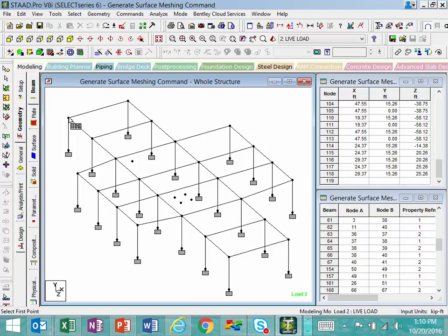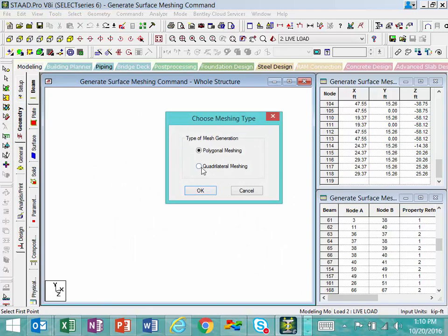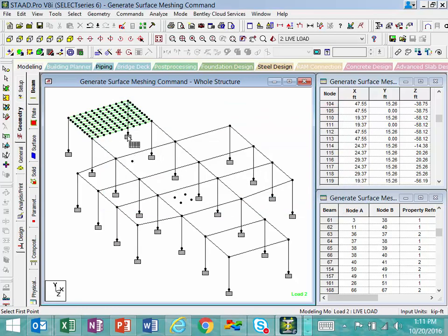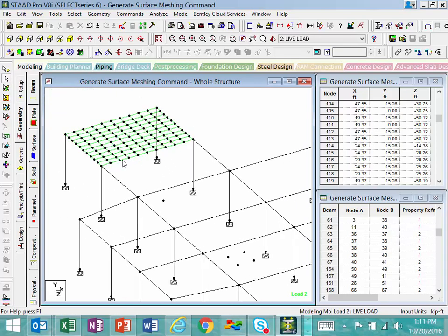So what that would look like is taking each one of these areas and generating its mesh. So here I can do each area, and then I may need to massage some things around, things like openings or extra point loads that I want to be considered. Only when you do it in a particular region like this, if I zoom in, will it segment your beams that are supporting it. That's what you're looking for. You're looking for these beams that are supporting the slab to be segmented and to share nodes with the slab so we have proper connectivity.